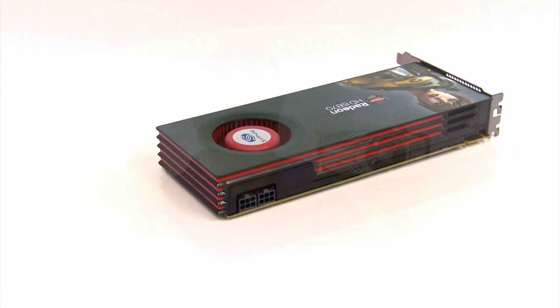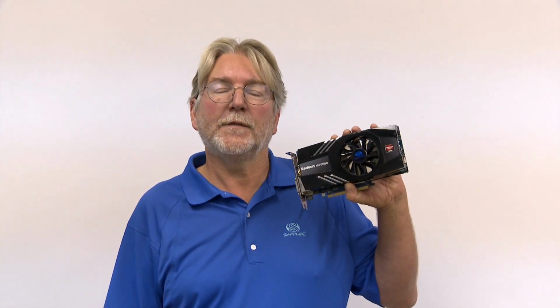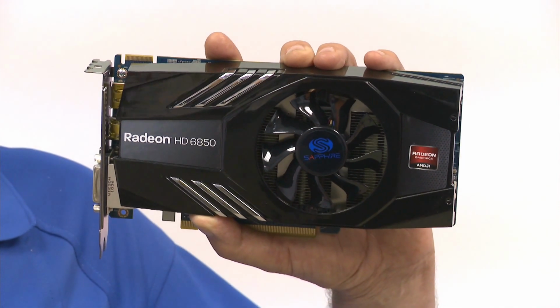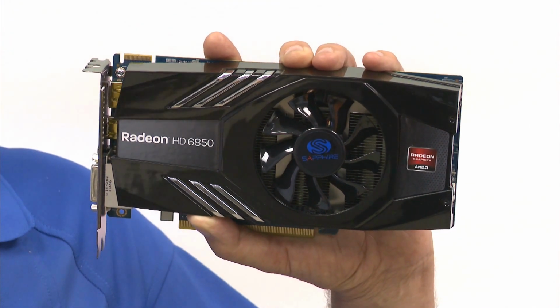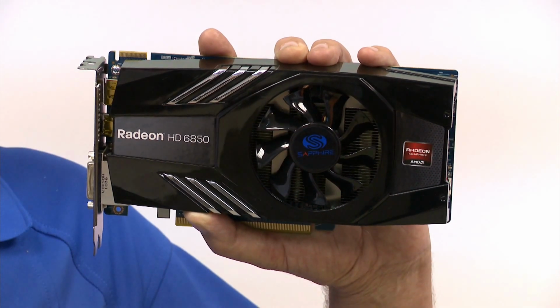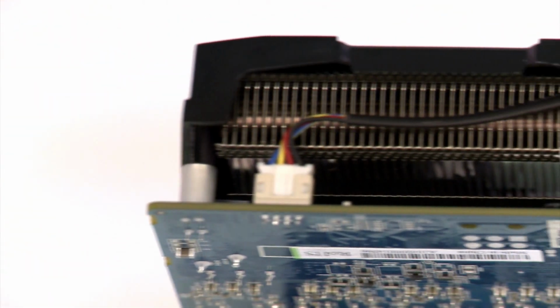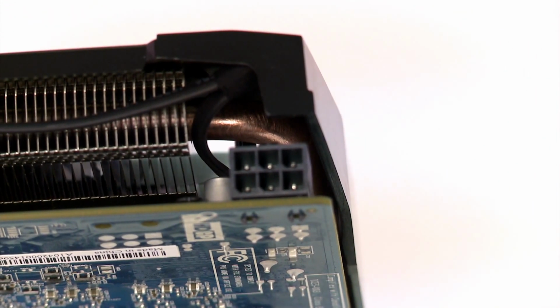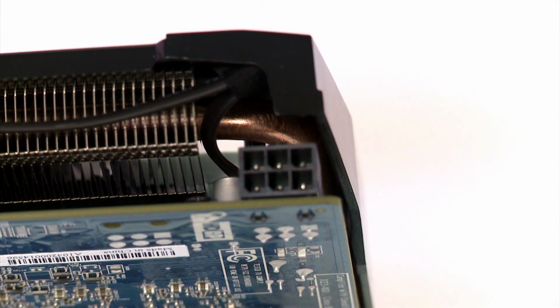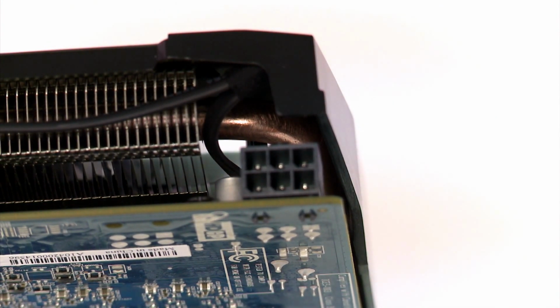The second card I'd like to introduce today is the HD 6850. The HD 6850 has a slightly smaller configuration of 960 stream processors and 48 texture units. It still delivers 1.5 teraflops of performance, and it's doing all of this for a power consumption of around about 127 watts. And again, with dynamic power management, this reduces to about 19 watts on standby. The lower power consumption of this card means that we only need to provide a single 6-pin power connector, making it suitable for an upgrade in a much wider range of systems.